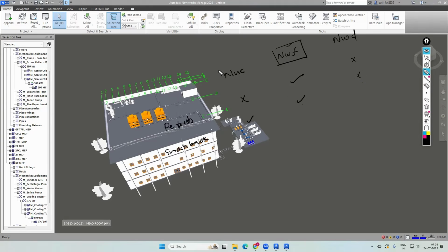Okay, so that's the difference between the Navisworks cache file, Navisworks file set, and Navisworks document. The NWC file will be automatically generated, or you can use exporter tools. The file size will be very small. Directly within seconds you can upload it in Navisworks, and the performance of the software will be good.